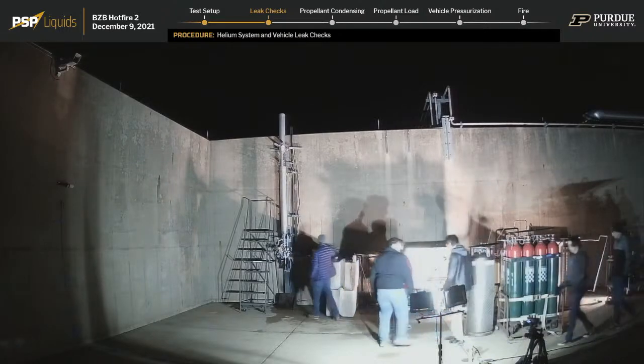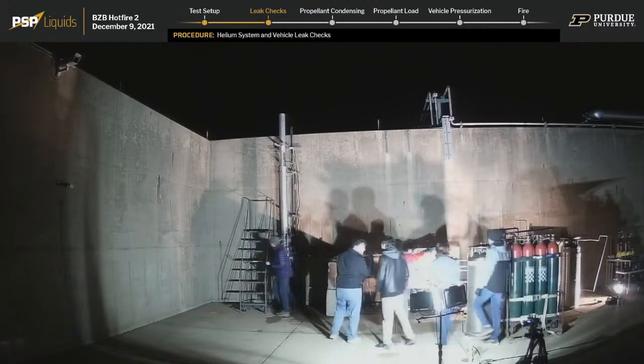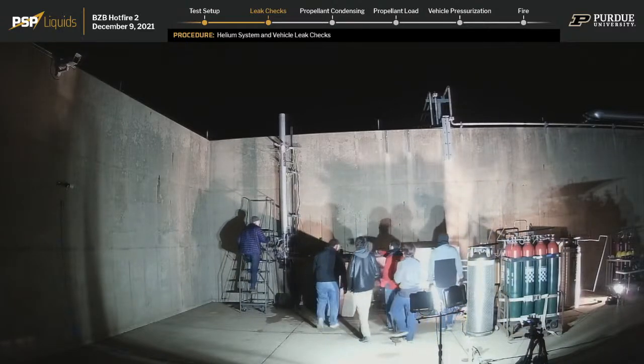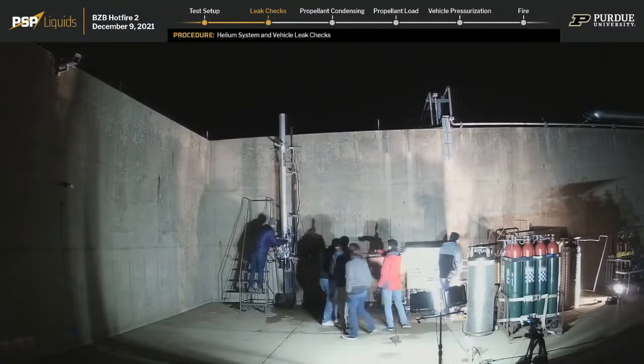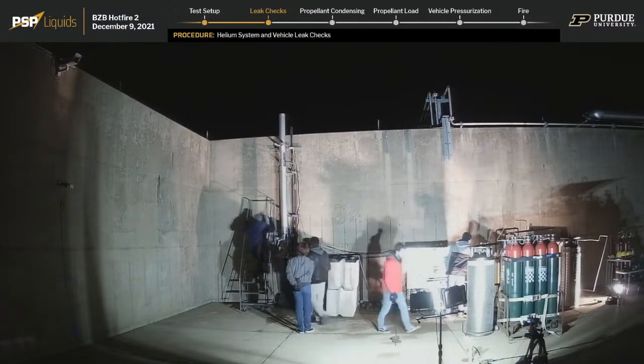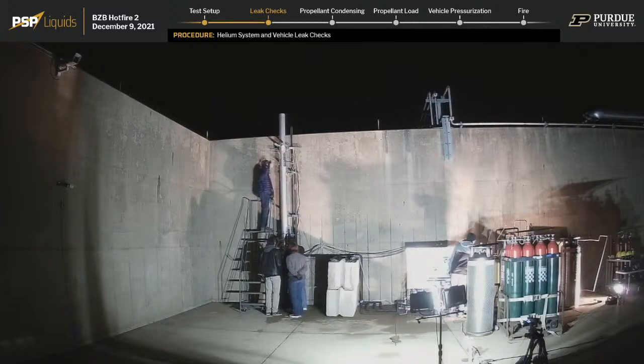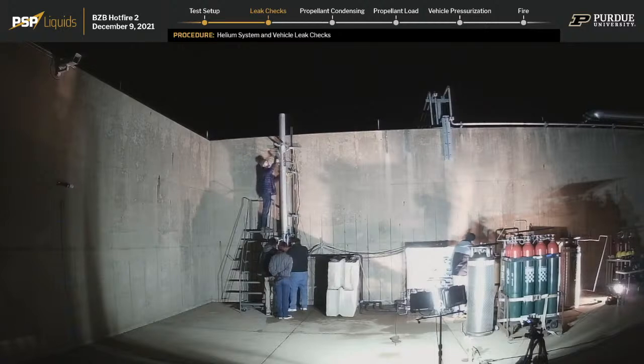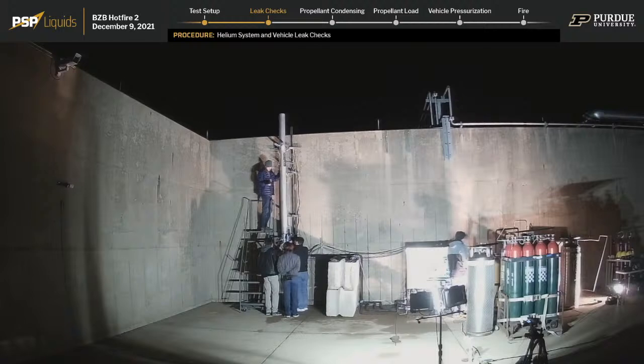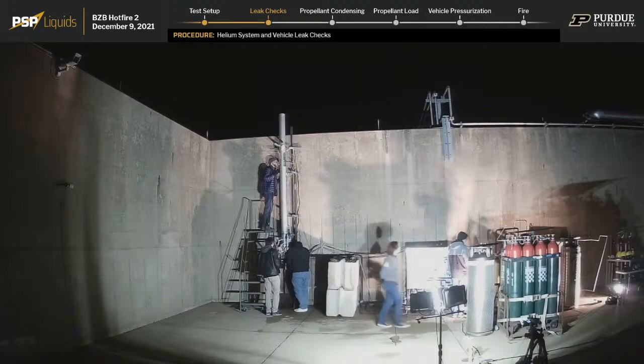However, this does mean we need to use an awfully high-powered radio system at the lab. Funnily enough, when we use the radio here in the media room, it actually turns off the monitors for the stream, so we will not be using the radio in here at any time. Another thing is, anytime we use it close enough to the DAC, all of our sensors jump around randomly. So people are often reminded to move away from the DAC, or we try to have the person with the walkie-talkie away from the DAC.